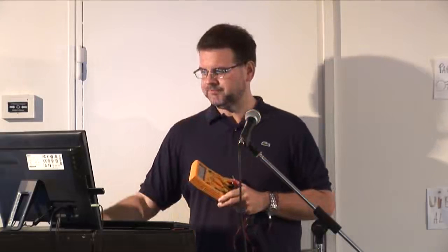Also, a source of error can be DC voltage applied to AC. Here you can see that the sine wave is not symmetrical anymore. It's shifted by the offset of the DC voltage. And regular multimeters can't correctly measure it, but true RMS multimeters can. I'm just showing you this so you can be informed about it.